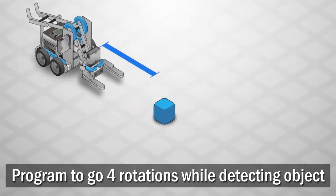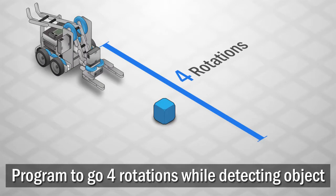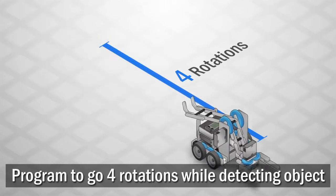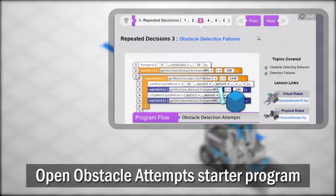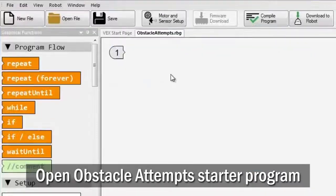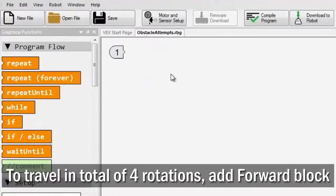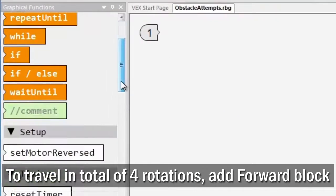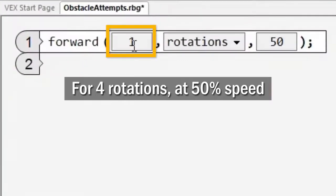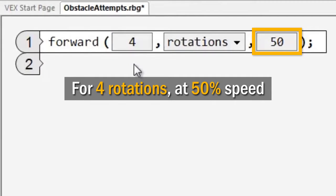Let's try to make the robot go 4 rotations, moving when the robot's path is clear and stopping when there is something in its way. Begin by opening the Obstacle Attempt Starter program linked to the right of this video. The main goal here is to move for 4 rotations, so let's try starting with a forward command block set for 4 rotations at half speed.